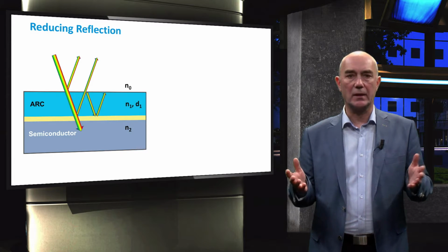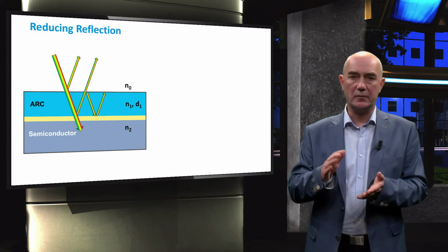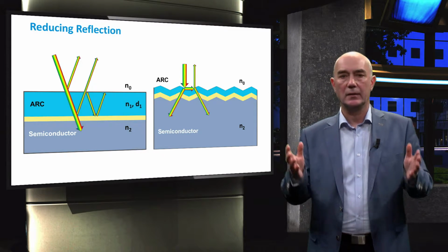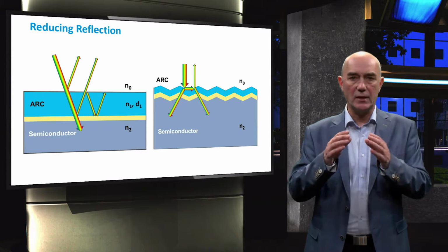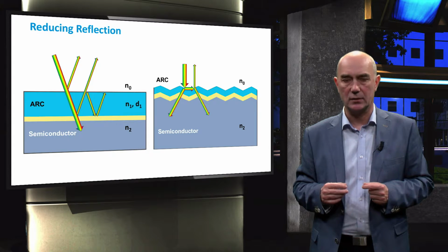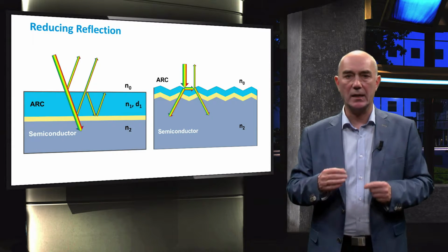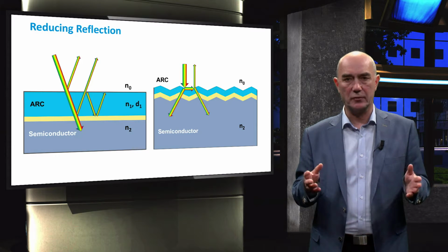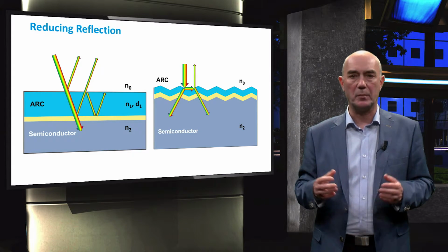Reflection losses can be overcome by adding an anti-reflective coating. Reflection can be further reduced by adding front texturing. You should remember, however, that there is a trade-off with front surface texturing. When you do this, you essentially add surface area to the solar cell, which increases the surface recombination. However, excellent passivation techniques essentially minimize this effect, so texturing is still a very worthwhile method for reducing front reflection. You can learn more about passivation techniques in the next course on PV technologies.